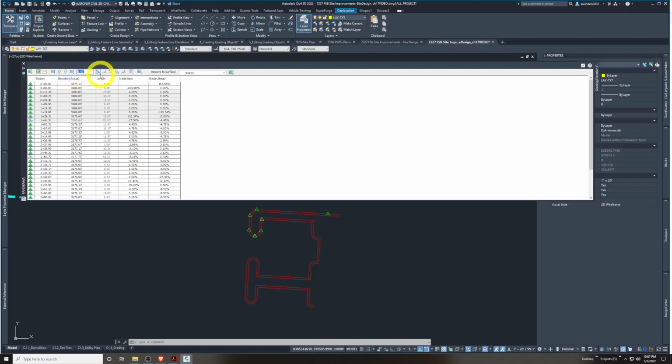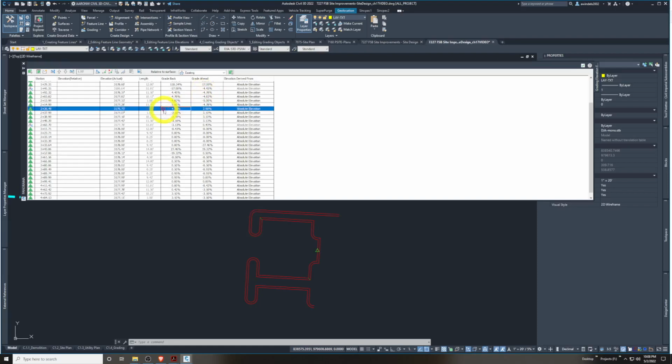Or you can use this to flatten it and say, hey, I want these to be a constant elevation or a constant grade, 0, 0, 0, 2, 2, 2 in one direction, 2% over that particular area. This is new to 2018. You can specify very specific zones or all points on a feature line and say, I want everything to match this other surface I just brought in. And that is pretty cool.